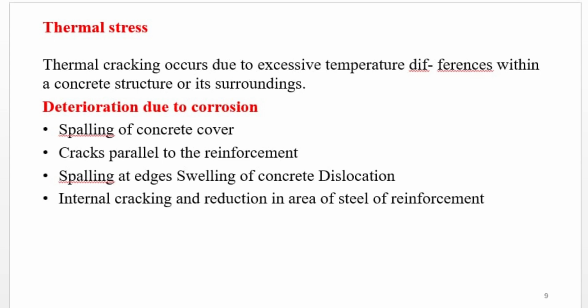So the quality of supervision also plays an important role. During the construction work, it should be carried out as per the specification. Adherence to the specified water cement ratio controls the concrete strength, permeability and durability. Insufficient vibration may result in porous and honeycombed concrete, whereas excessive vibration may also lead to segregation. So we need good quality supervision during the construction process.